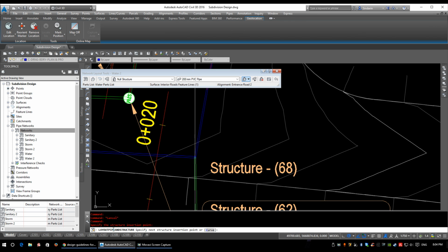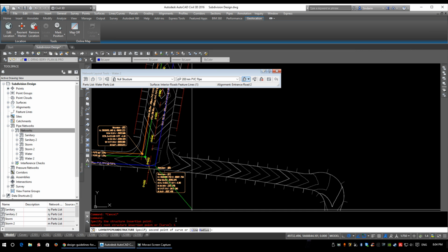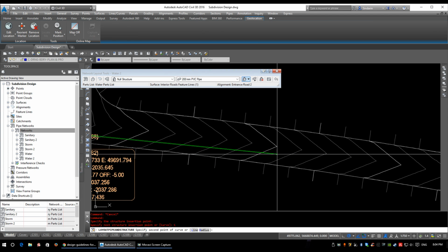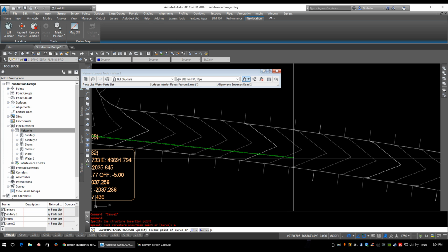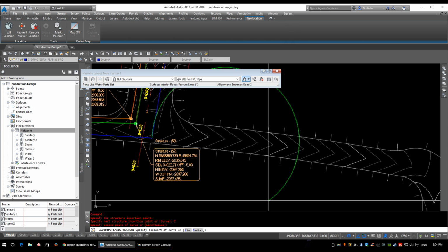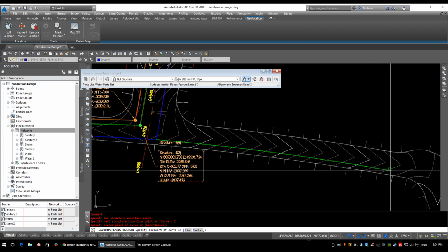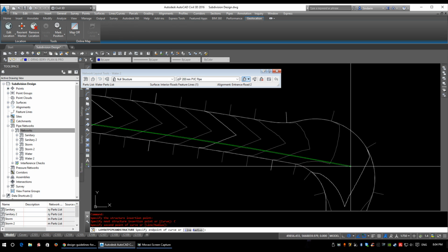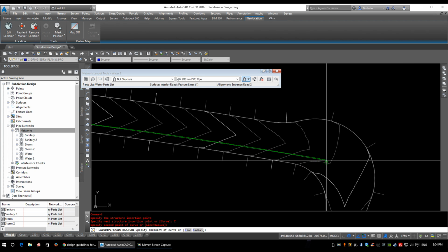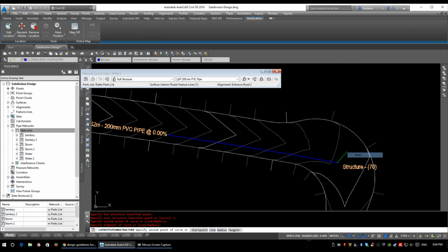And if you look in the command line, we're going to click on curve. So we want to curve this pipe. So select second point of curve. So like drawing a polyline, you select to about the midpoint of the curve. And as you see, my pipe now bends. Now we have to keep track of the proper radiuses to make sure we meet them. So I'm going to put the last piece of pipe in, and I'll show you that radius page. So I put that in, I'm going to hit enter.